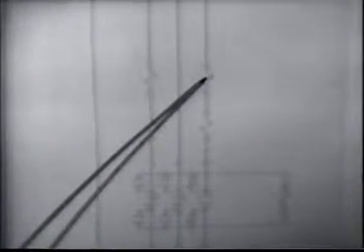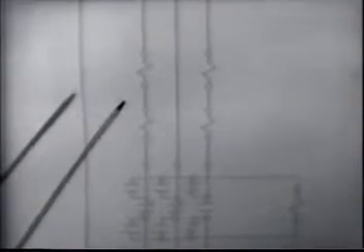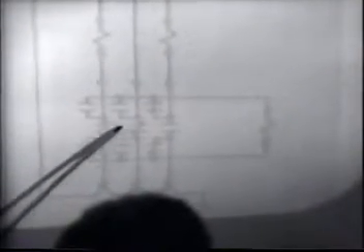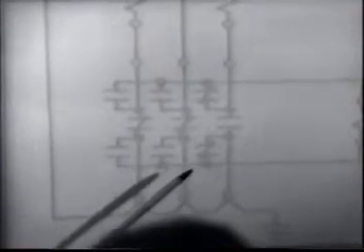This is the current elements of the watt meter. These are the current elements of the var meter. This is the current element in the ammeter. And this is the ammeter switch, which should be shown to show the current from one phase switched to go through the ammeter. So we can trace the path of current flow in this particular circuit, transformer down through the current element of the watt meter.